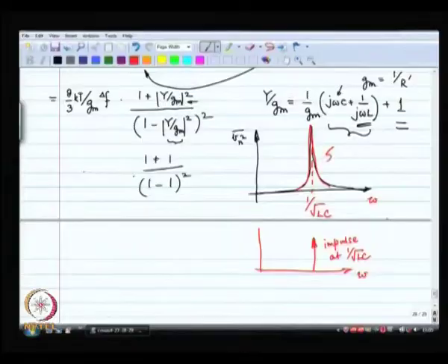All of this is really called phase noise. In a real oscillator, all of this extra stuff is called phase noise. Why is it called phase noise? Because there is no noise in the amplitude, the noise is only in the phase. The amplitude is the amplitude of a square wave, there is nothing to be said about the amplitude.